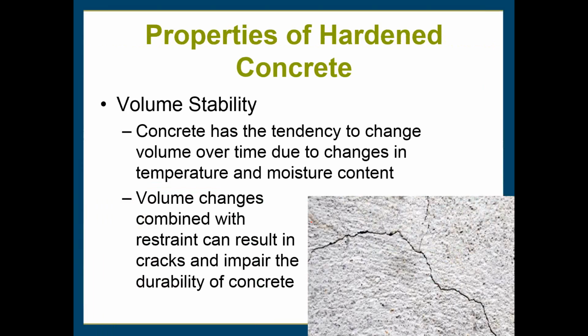Additionally, volume stability. So we talked about how when concrete is exposed to freeze-thaw cycles, the water in the concrete will expand when it freezes, and if that's not taken into consideration when the mix design is made, it can have really negative effects and cause an increase in volume that the hardened concrete can't compensate for, so it results in cracking.